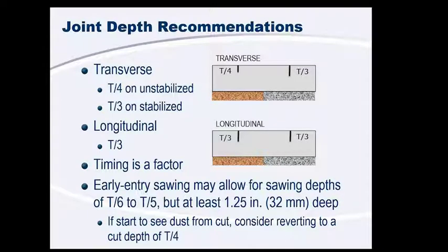And we really need to make sure that the longitudinal joint activates the way it should, because as we saw in that previous slide, the longitudinal cracking that can come off there is typically going to end up right in a wheel path and be very detrimental to our pavement performance.